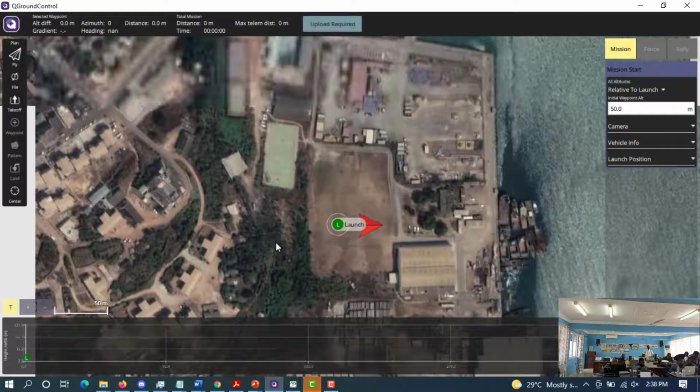Now, confirmation. So for this drone, if you are going to start a mission and the wind speed around us is more than 50 kilometers per hour, don't fly it. It's just like you are traveling and then there's a delay at the airport because they're telling you the weather is not good. This one too, the weather is not good. So when the wind speed is more than 50 kilometers per hour, you don't fly. That is the requirement.